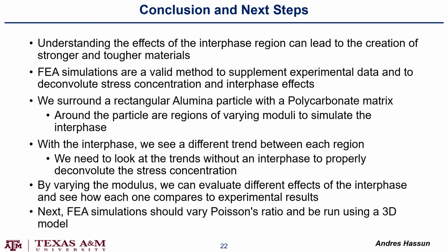By varying the modulus, we can evaluate different effects of the interphase and see how each one compares to experimental results. And next, FEA simulations should be run varying Poisson's ratio as well as moving into 3D models.